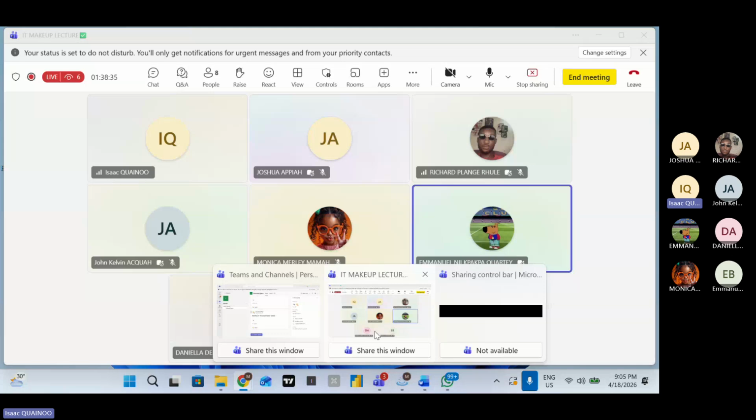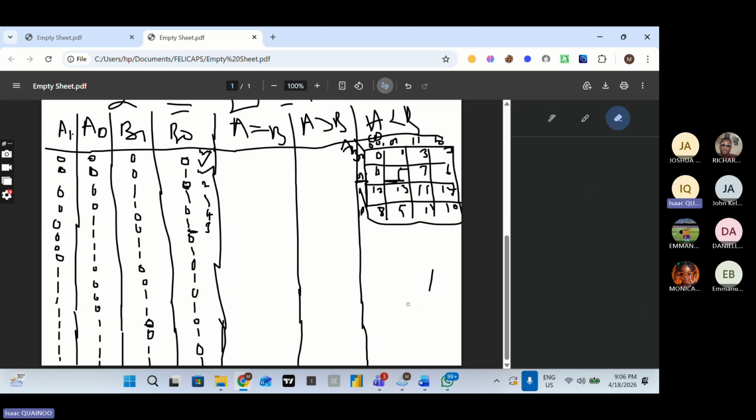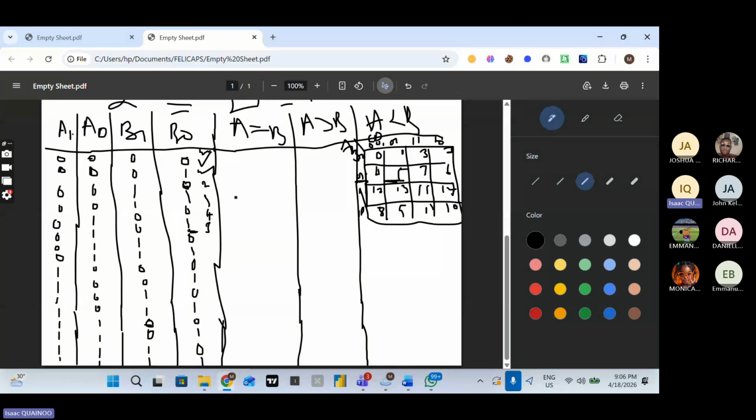Okay. So I was illustrating why arranging everything in the correct order is very important, and even missing the arrangement of a line properly. All the combinations can be correct, but the arrangement is not correct, and you proceed to minimize using a K-map, the resulting answer would 100% be wrong. I was explaining that it is because when you take K-maps, each cell is numbered intentionally to correspond with the arrangements of inputs on your truth table.